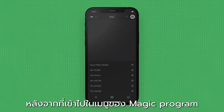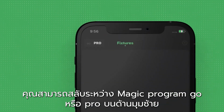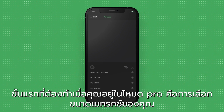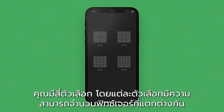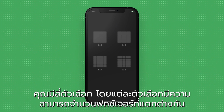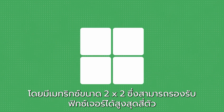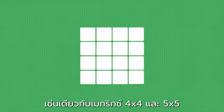After entering the Magic Program menu, you can toggle between Magic Program Go or Pro in the upper left corner. The first step once you're in Pro mode is to select the size of your control matrix. You have 4 choices, each with capacities for different numbers of fixtures, including a 2x2 matrix which can hold up to 4 fixtures, a 3x3 matrix that can hold up to 9, as well as 4x4 and 5x5 matrices.